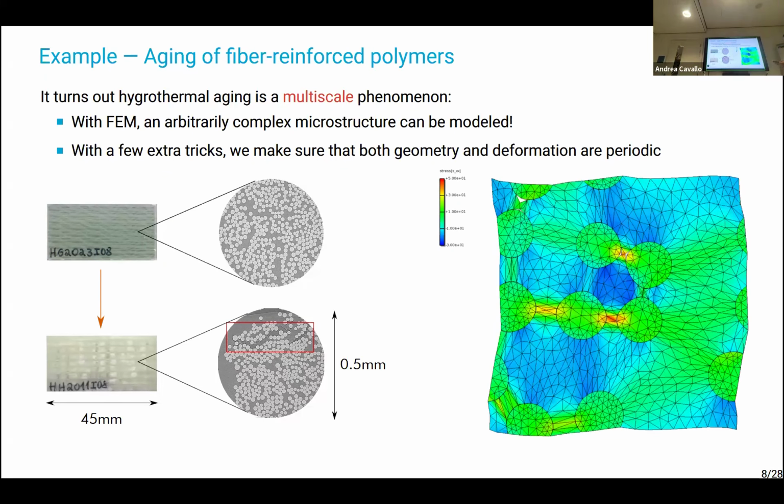And you can see it swelling, right, as it absorbs water. And then I use very complicated material models in here to model how the material breaks when water comes in. That's why, if you look here, some fibers are detaching from the resin. And also here you can imagine the fibers coming out of the screen that way. So a very detailed model at this scale. This takes about an hour to run.